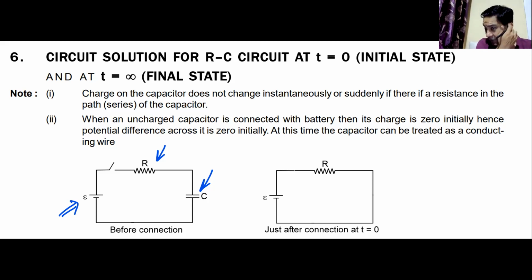Now, if I think of a capacitor as a resistor, now a capacitor is definitely not a resistor, but a capacitor does offer resistance to the flow of current. If you talk about AC circuits, AC current or AC voltage, we call it capacitive reactance. Yes or no? Yes, sir. Similarly, for the sake of argument, when the capacitor is getting charged at time t is equal to 0, and we will see it through the equation, the capacitor behaves as a short circuit.